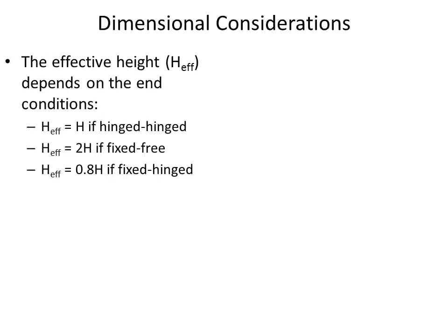If it is fixed hinge, theoretically speaking it is 0.7 h, however practically speaking you take it as 0.8 h. Fixed is something extremely rare to find. This is why it's not included here, because it's not practical at all.